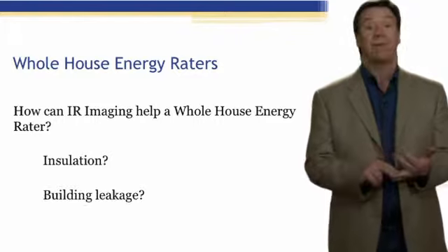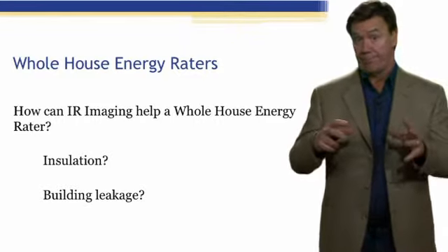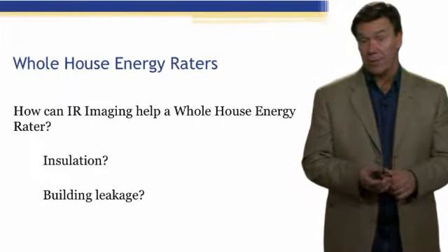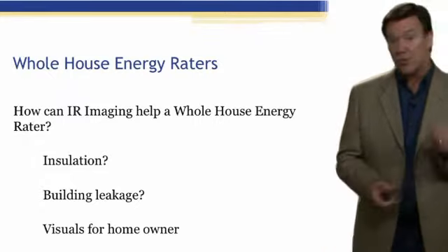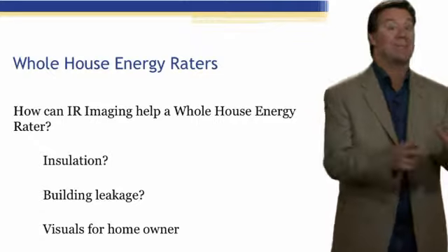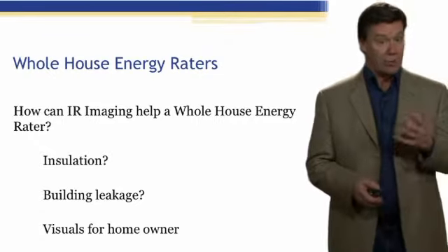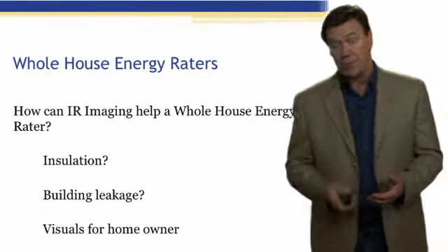How can IR imaging help a whole house energy rater? Well, number one, it helps us find defects in the insulation. It helps define building leakage in terms of big problems associated with air leaks. Also, it helps provide great visuals for the homeowner. In addition, a really important factor of IR imaging is that it helps us determine how good of a job we did at fixing the problems. So we can actually show the homeowner that we did the job we said we were going to do.